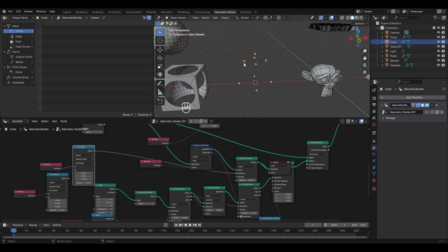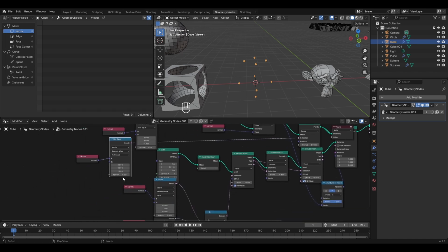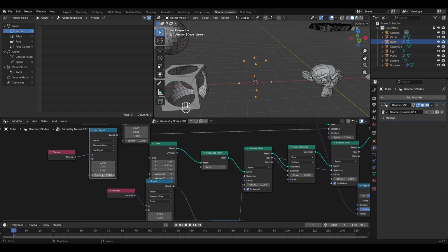And also here you can see that these 4 points are actually the points lying on the faces of the rooftops. And to remove these, we'll take the second compare node again and connect it to the selection, and here you have the option of epsilon in the compare node. And if I slightly increase it by holding the shift button and dragging it like this, then at one particular point you will notice that those 4 vertices will disappear.